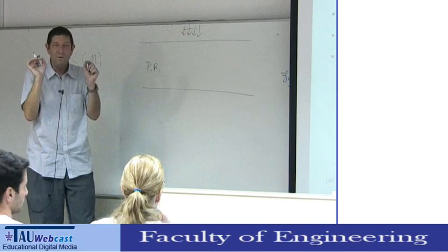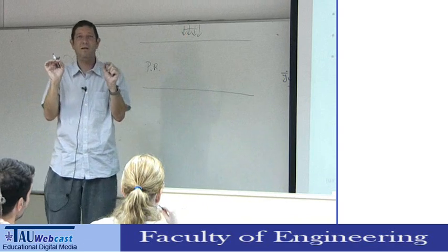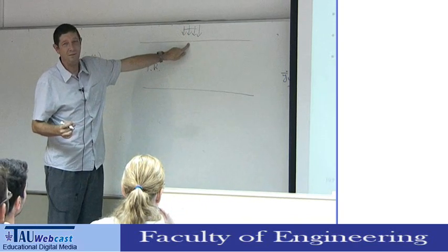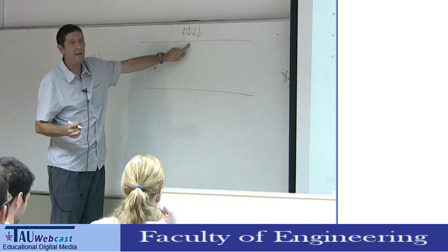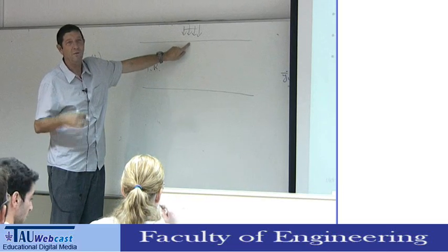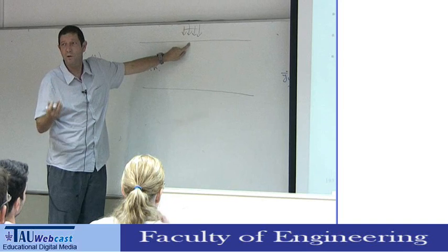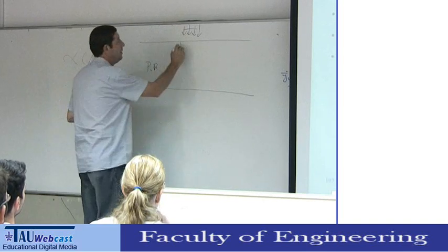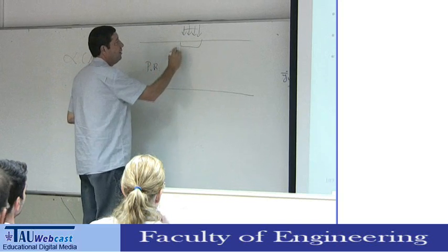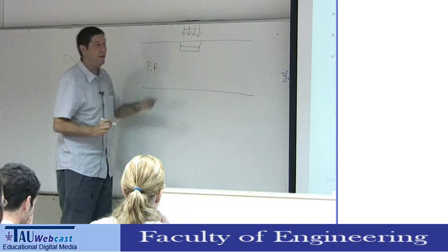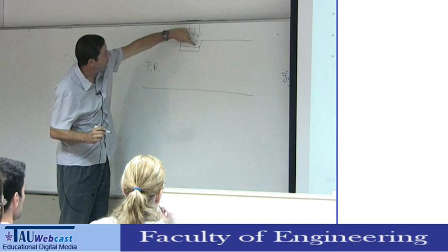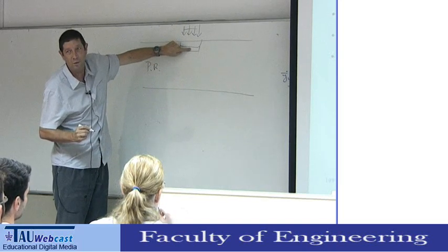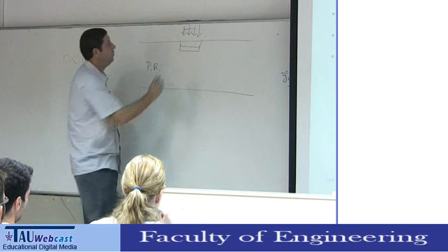I would like you to think about the effect on the photoresist. In this area we have light. Because we have light here, in this area we destroy the absorption component, so this area becomes transparent. So we expose the area below it. Every area which we expose becomes transparent. Then we expose the volume below it, and the volume below that.